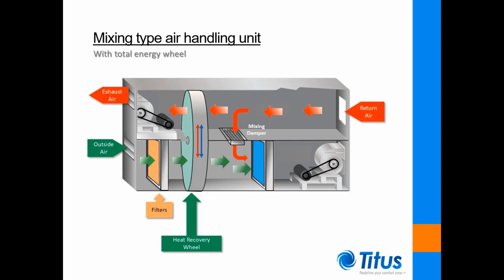The outdoor air is then mixed with return air by means of a damper within the air handling unit. The volume flow rate of the return air passing through the mixing damper is adjusted according to the supply air delivery requirements of the air handling unit. The mixture of outside air and return air is then cooled, and in most cases dehumidified, as it passes through a cooling coil. Finally, the blower within the unit discharges the conditioned air mixture into the supply air duct for distribution to the spaces it serves.